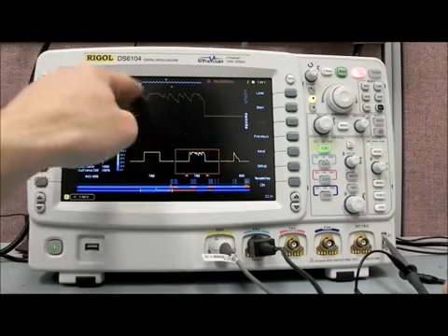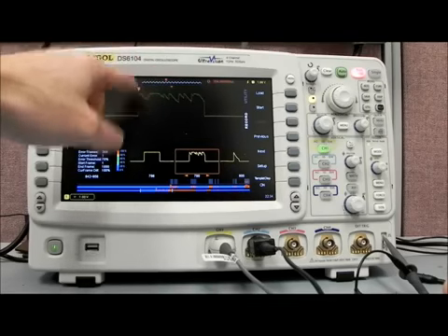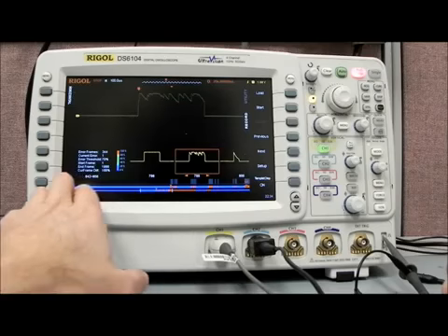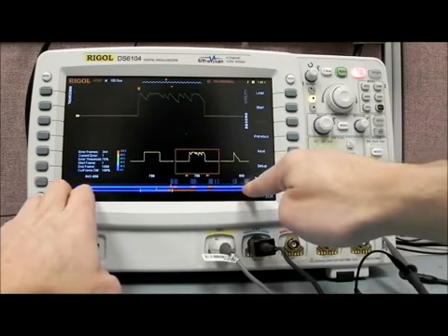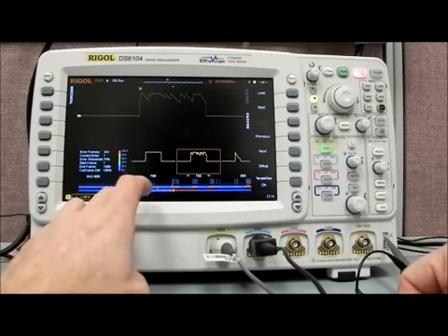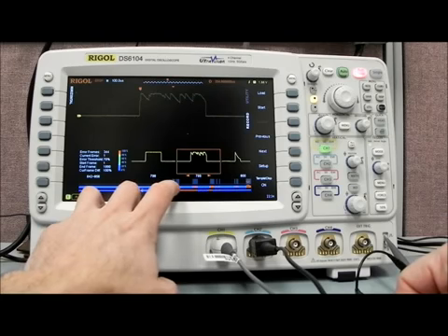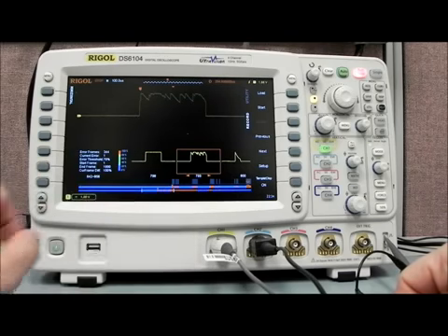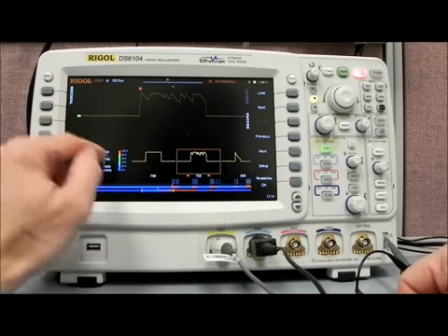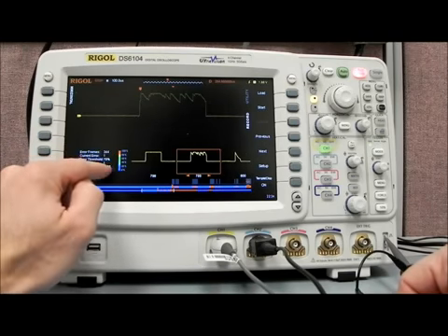You can see that based on our mask, quite a bit of the waveform is analyzed outside of the mask. On this bottom line, this is the entire waveform recorded memory, and the red denotes areas that have failed, and the blue denotes frames that are good. The center area is a zoom into the different frames that have failed, and on the left-hand side it tells us how many error frames we have. So this is 344 out of the total, which was 1,890.